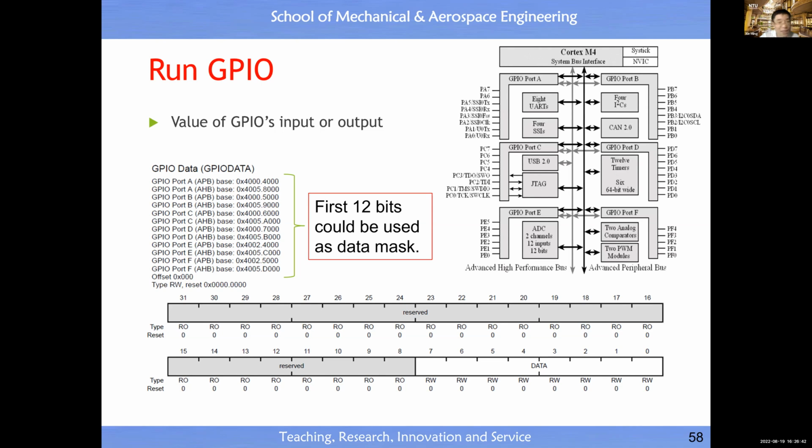It's very interesting. You look at the address here. Do you see the last 3 digits are 000? So this is a hexadecimal number. 1 digit of a hexadecimal number corresponds to 4 bits of a binary number. Then 3000 in hexadecimal tells you that there are 12 bits. 3 times 4 is equal to 12. It means inside the address, 12 bits are not being used.